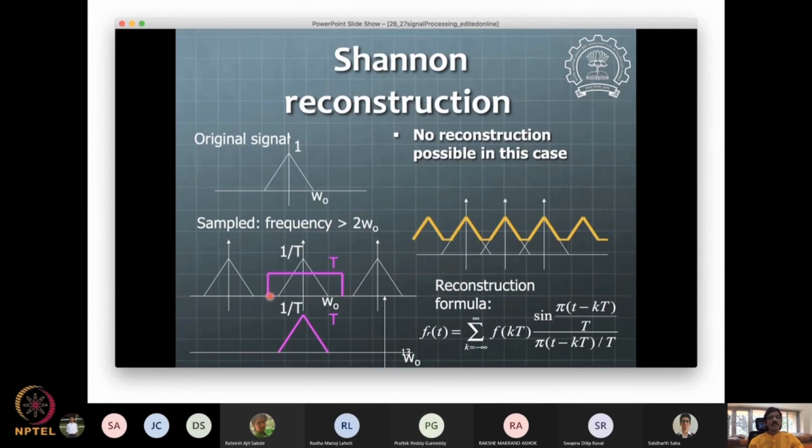When I say the filter is of this rectangular form, then this particular filter function in the frequency domain multiplies the frequency domain response to produce the output of the filter. That's how one can think about it. It's like an input getting into a transfer function, and the transfer function modifies that input and produces some output. So every system from that perspective can be seen as a filter also.